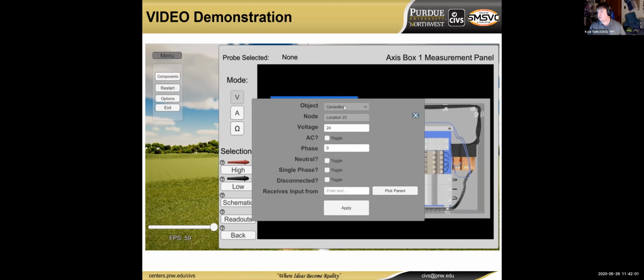All of those things are inputs that get fed into the digital multimeter, and ultimately that'll decide what the digital multimeter will spit out. That's something I could probably spend another half hour on in a separate webinar, talking about how that happens in the background of the simulator. But just know that the multimeter in the background is smart enough to know, hey, I'm measuring a three-phase system to a neutral, so I'll do the line to neutral calculation for you.